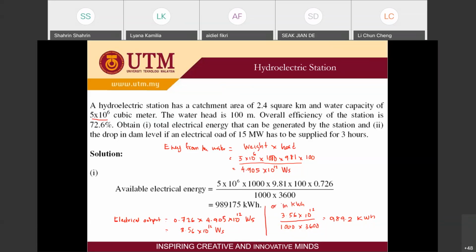Okay, because usually the electrical power engineers only know kilowatt hour. Okay, they appreciate it more if the unit comes with the kilowatt hour. So please refer back to the thermal coal, where as you can see, in all the calculation involved in the coal calculation, all the units are in calorie. But when it converts into electrical output, it needs to be converted into kilowatt hour, because we know that 1 kilowatt hour is equivalent to 860 calorie. Okay, so this is actually from the coal.